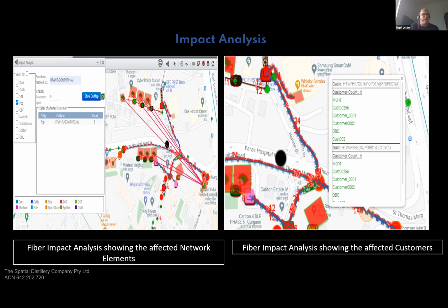One of the other things inside Network Access I must mention now is also OTDR tracing. So inside the network, we do store information like around the loops. So if you've got loops of cable that are sitting inside a pit, manhole, we store that level of detail. So if there is a physical break and you do an OTDR trace, you'll be able to accurately identify where geographically that break would be, because it's considering the true length of the fiber using the loop lengths as well.